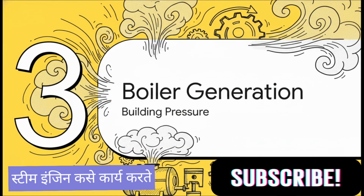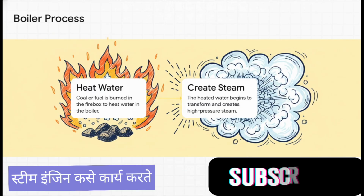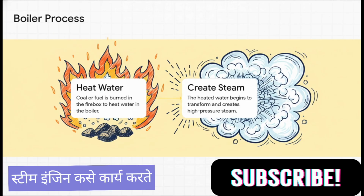Section 3. Boiler pressure generation. All right, here is where the engineering process really kicks in. Step 1. Coal or fuel is actively burned in the firebox. This creates intense heat, and that heat is directly applied to the water sitting inside the boiler. Step 2. That heated water starts to transform, creating high-pressure steam. Think about what's happening here. We are taking raw, uncontained heat energy and transforming it into a highly contained, incredibly intense physical pressure inside that boiler. It is a massive buildup of internal force just waiting to be unleashed.